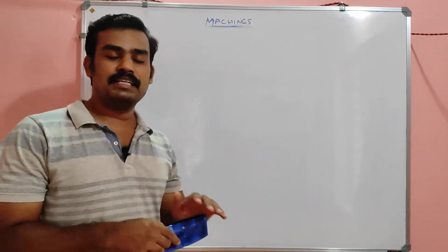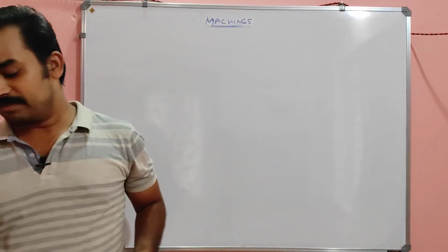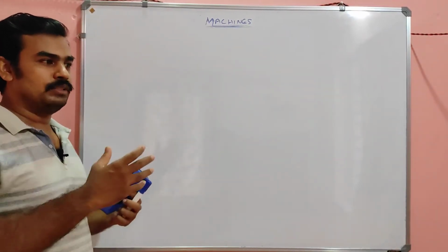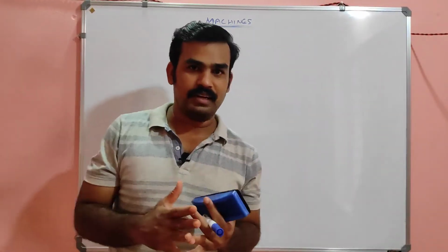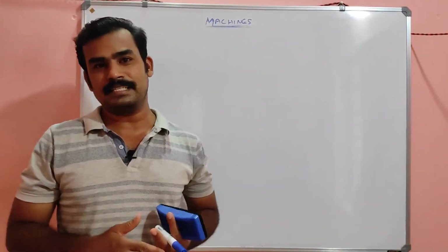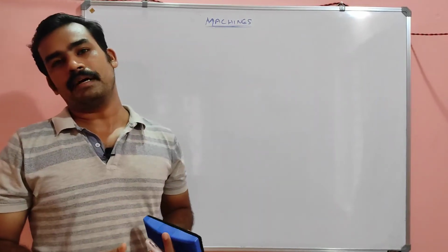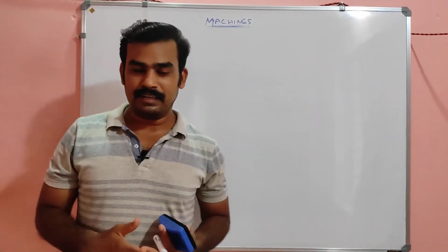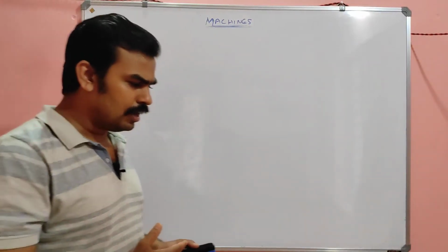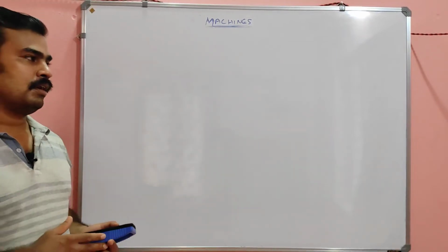So in the last class we discussed the armature reaction, and we clearly discussed commutation and how this armature reaction and commutation connect, and how we can eliminate the armature reaction as well as the commutation problem by using interpoles, by using compensating winding, etc. So these are the methods to eliminate such bad events that occur in the DC machine.